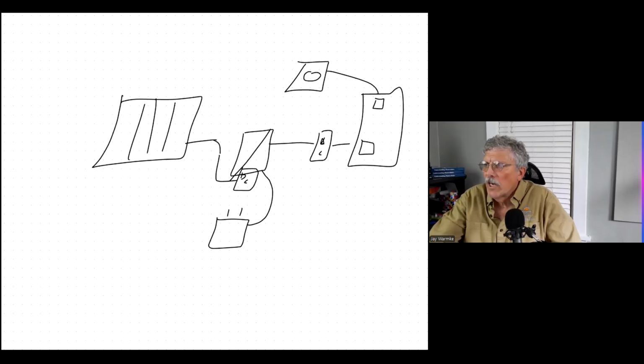If it needs to charge the batteries, it doesn't go through any conversion. It just goes straight DC to the battery. Then from the battery or from the array, it can be converted to AC and go to the loads. So there's only the one inversion, the one transformation between DC and AC, and that's when it leaves to go to the loads. But between the solar array and the batteries, everything is happening in DC.